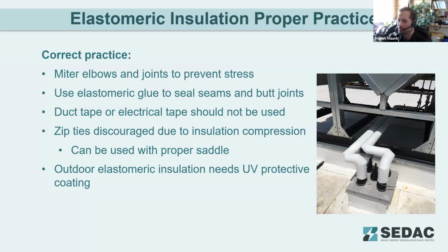So make sure when you're installing these that you have proper thickness, you're mitering those joints, and when you're butting these joints together, you're using an elastomeric rubber cement to seal those joints together. And then you're providing that protective coating on the outside as well.